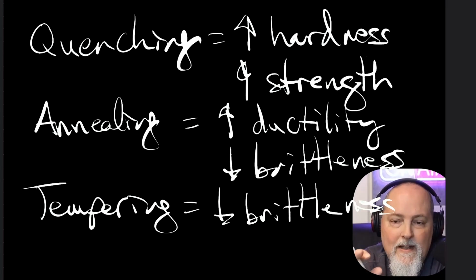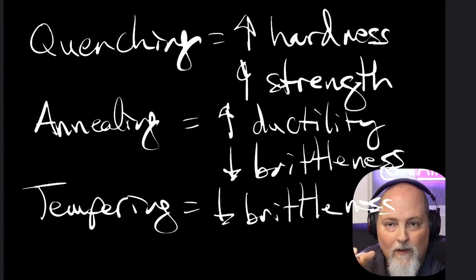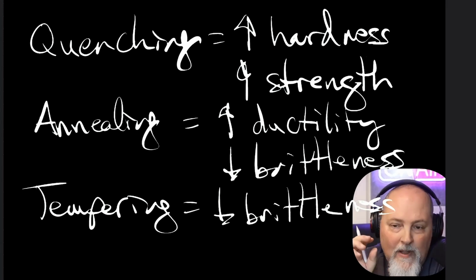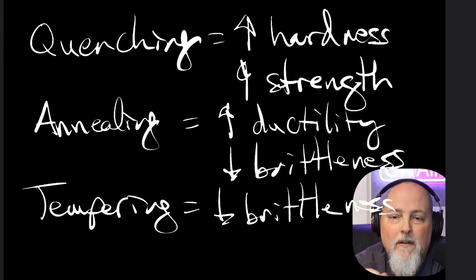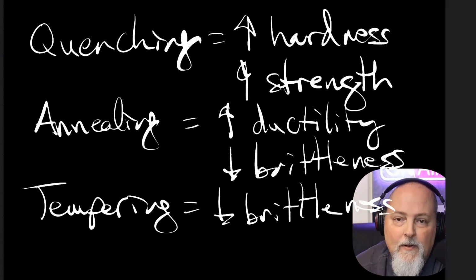Just the main idea is that welding changes the local structure, whatever that grain structure is. At the point where you're welding it, you're introducing a lot of heat and you're changing those local structures and its stress states. So welding is complicated because you have to be careful with your preheating, with your cooling, to reduce the damage. All right, let's pause here for a question.